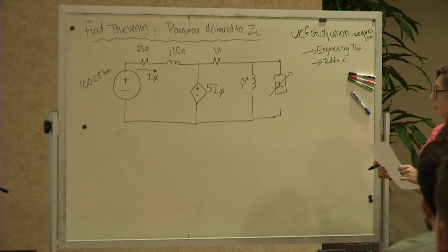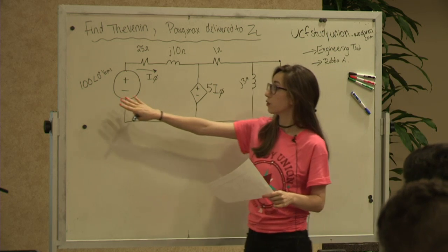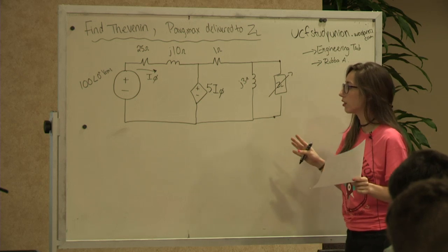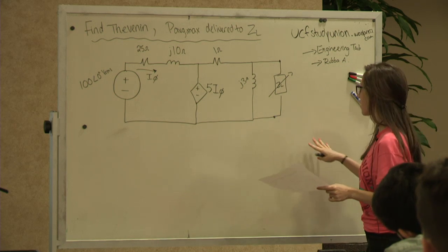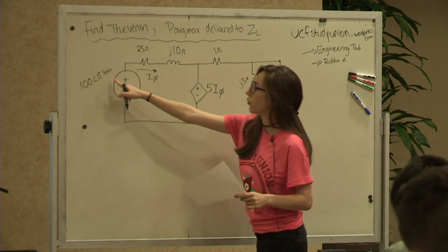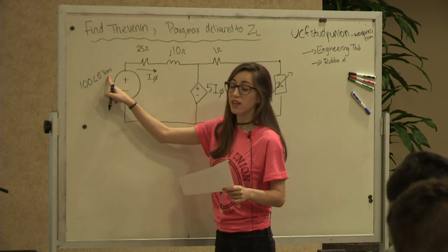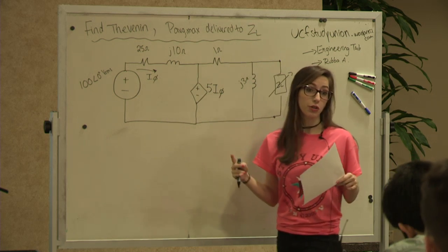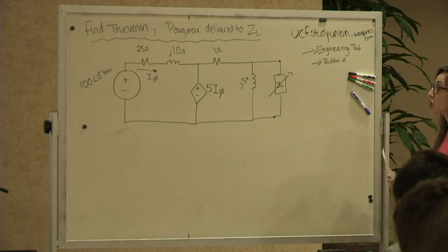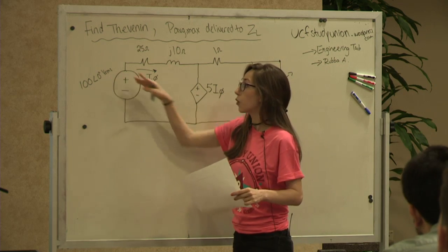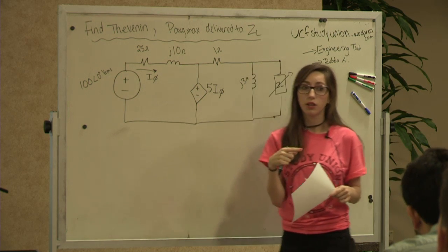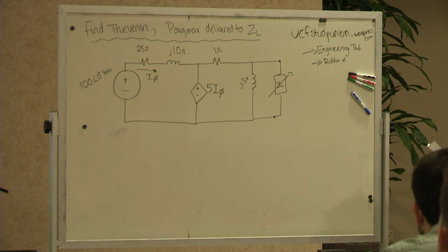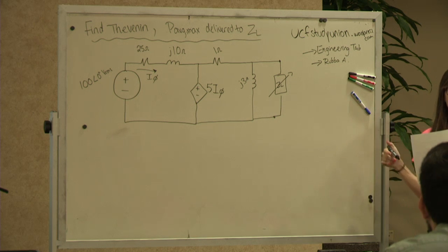So this is a phasors problem, and notice that they give you your voltage. They give you all your elements. They're already in the phasor domain. You don't see any cosine, nothing function of t. It's already in the phasor domain for you. And also notice that this is VRMS, so they've already converted it. They took the voltage and they divided by √2, so that's already included in that VRMS value. So when you're solving for power, or when you're solving for IRMS, you don't need to worry about putting the √2 under that, because it's already included. Any questions about this circuit before I start?